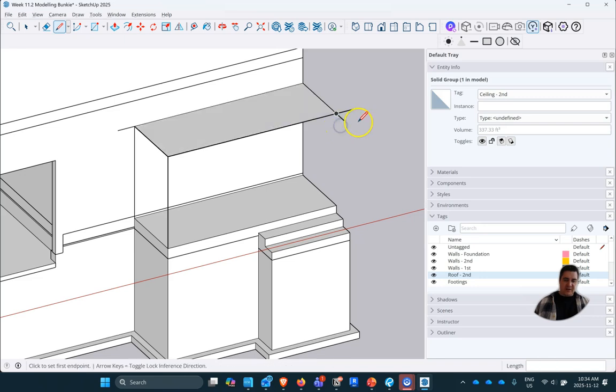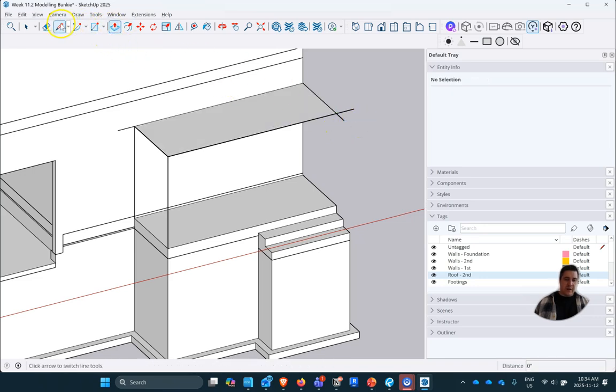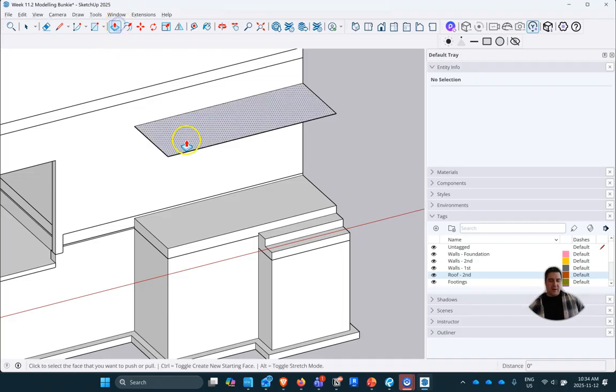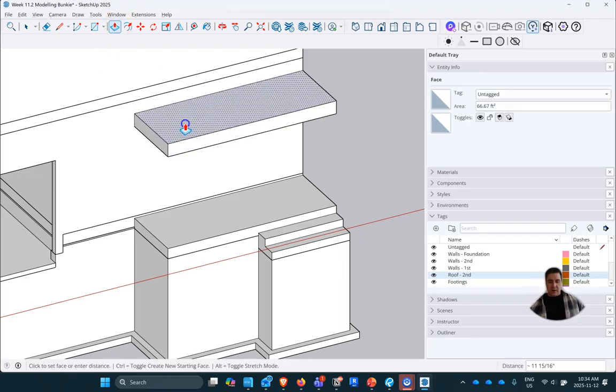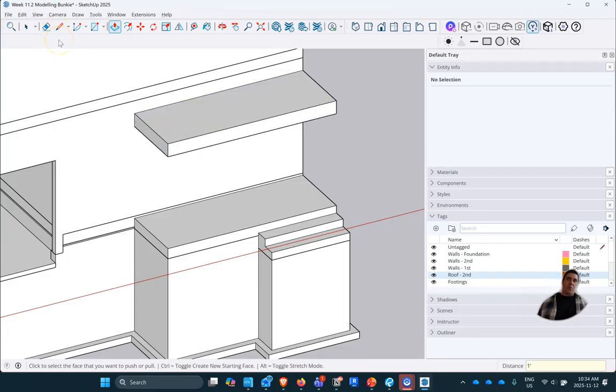And again, I'll just model stuff past in order to get a rough understanding of where that element is. And we can eliminate some of these lines. And so let's move this up 1 foot. And with our beams, as I mentioned when we were looking at the drawings, we had two 2x8s, and so we're going to go up 7¼ inches. The reality is, you're probably going to end up putting some decorative element around that as well. But I'm just going to model those beams only for now.